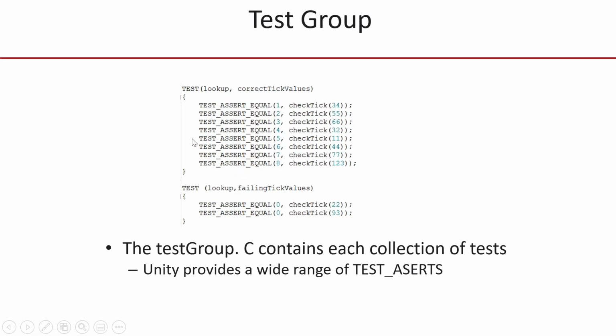Okay. So here we'd be writing our C code, and then we're writing test cases to go alongside that. So Unity works as a very good, what I would call a developer test framework, so that you can write C code, write tests to go around it, and then every time you go into the debugger, you can run those tests to check that you haven't broken your code. And even if you know it works, by going through this process, you will find ways to improve your code. And again, we've used it on a number of projects, and it's been quite effective as a simple test framework.